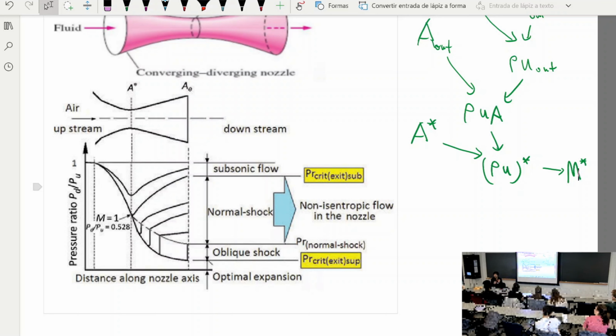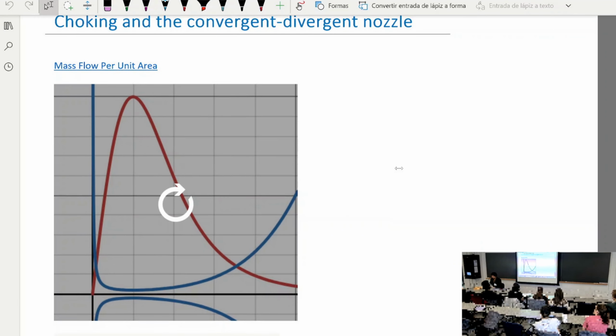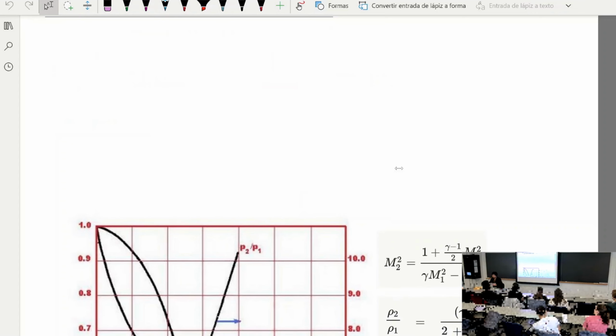Okay, and the diffusion. Because of the shock wave, on one side it is supersonic, the other side is subsonic. There is a huge speed difference. So the average speed of the molecules is different. So molecules crossing the shock wave transfer momentum through viscosity, and anything that involves significant viscosity is not going to be isentropic.